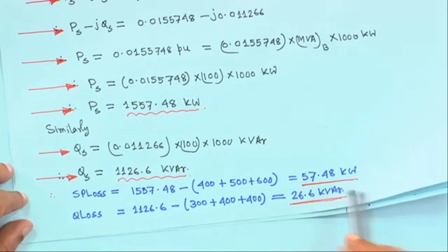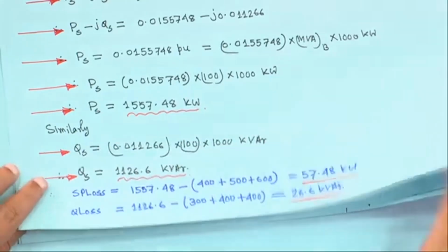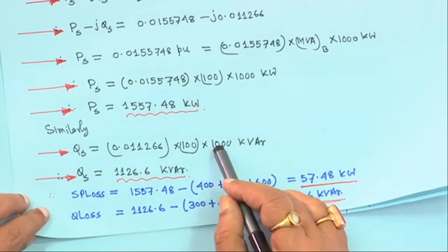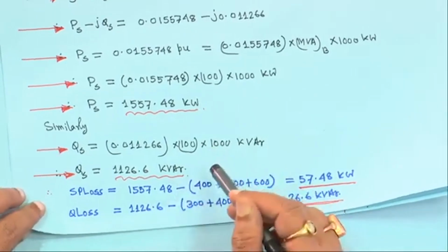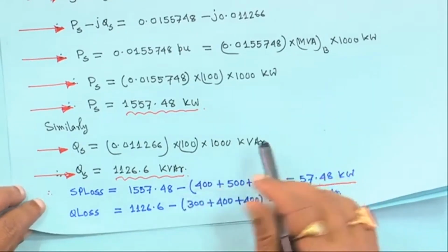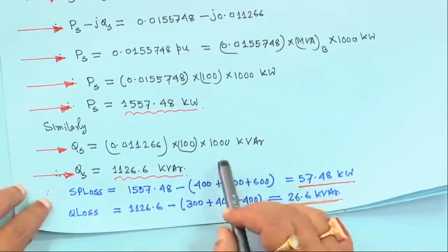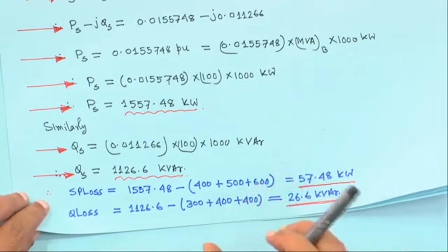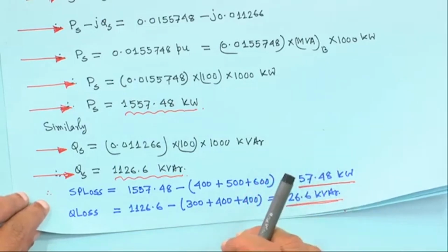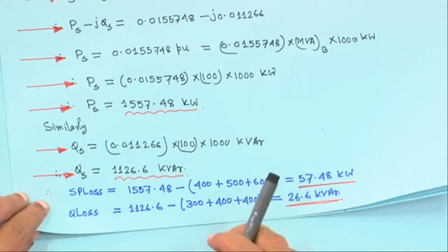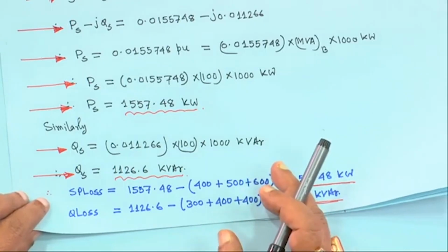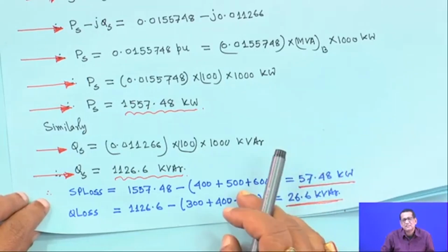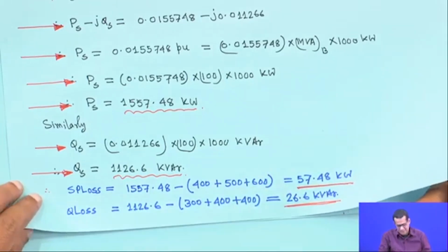This way loss can be computed. Here, during the iterative process, I did not check any convergence, because then I would have to move one more iteration. I request you to do the next iteration yourself, right. Iteration means that you take the difference of the loss in successive iterations, take the absolute value, and if it is less than say 10 to the power minus 3 or minus 4 in terms of kilowatts, then you assume the solution has converged.